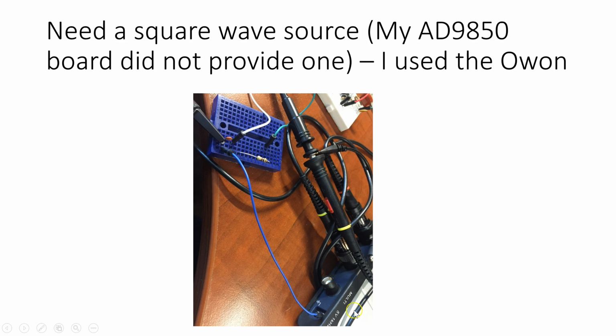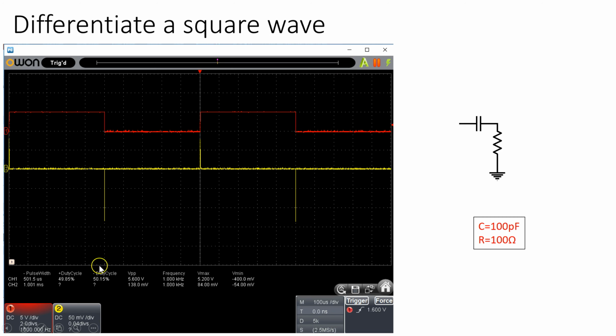So for our source of square waves, I'm using the calibration signal that is output on these little tabs on the scope. It's 5 volts at 1 kilohertz. I've taken that here. This is my differentiator with a 100 picofarad capacitor, 100 ohm current sensing resistor, and this white lead goes to the second channel on the scope. The first channel is connected here and measures the voltage across the whole circuit. So let's take a look at this differentiator using the 100 picofarads and measuring the current through the circuit by measuring the voltage across the 100 ohm resistor.